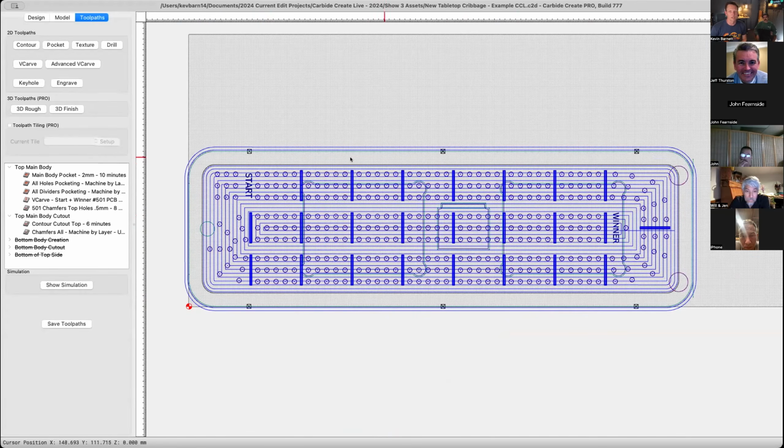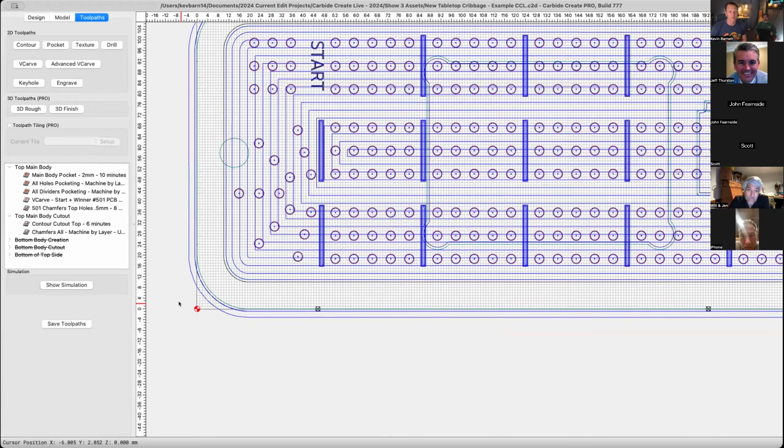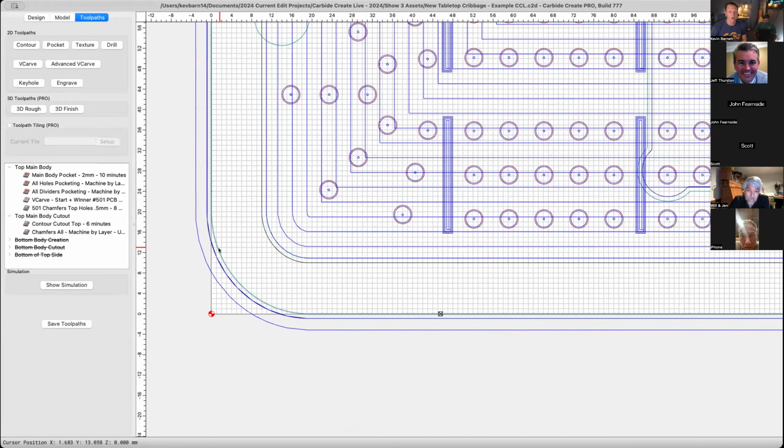when you're flip machining, you want to make sure that the edge of your object is on the edge of the point here, lower left, of your setup. And because you can use a bit 0 to locate the exact XY coordinates here.